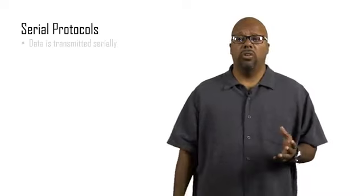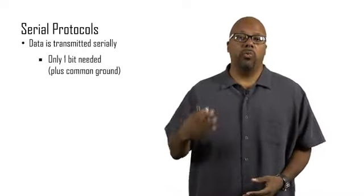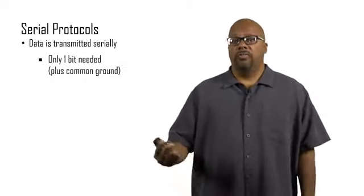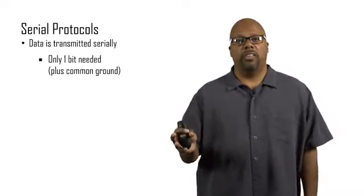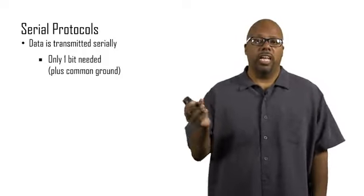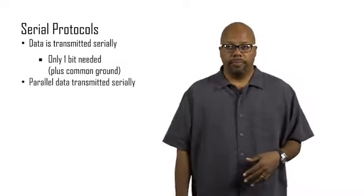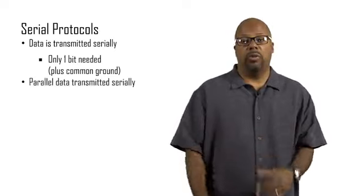A serial protocol, in general, is where you transmit data serially. You transmit data one bit at a time, or one chunk at a time. In our case, one bit at a time, instead of, say, 8 bits at a time. The Arduino's microprocessor, the ATmega328, is an 8-bit processor, so each chunk of data is 8 bits. But we're going to be transmitting 1 bit at a time. So why would we do that? The parallel data, 8 bits parallel, is going to be transmitted 1 bit at a time.